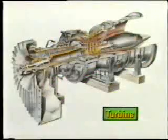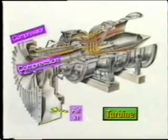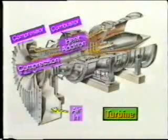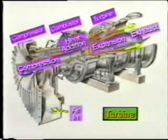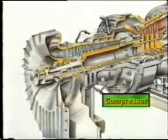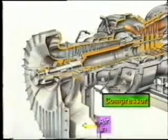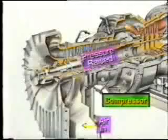In this basic gas turbine, there are actually four processes that take place. That is, compression in the compressor, heat addition in the combustion chambers, expansion through the turbine, exhaust to atmosphere where heat is lost. In order to help us get a better feel for the operation of the unit, let's consider some typical values of pressure and temperature. To begin the cycle, air is drawn in from atmosphere through an air filter into the compressor. As the air passes through the compressor, pressure is raised.